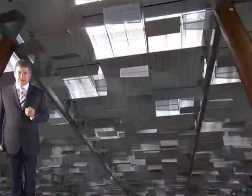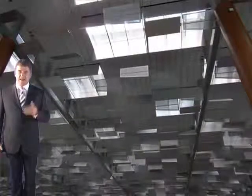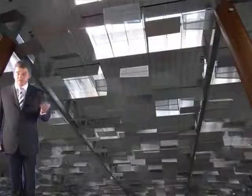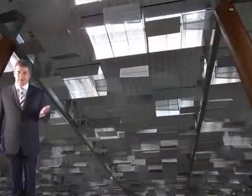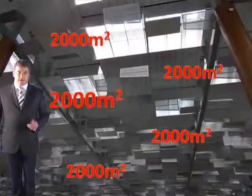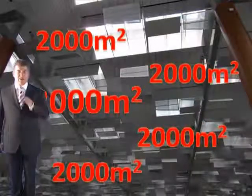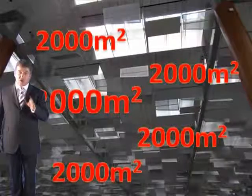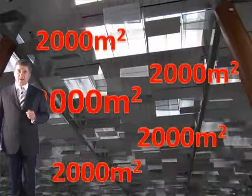Now the first thing to determine is the number of reservoirs that you're going to need in your building. So you need to work out how many reservoirs. For cost reasons, again, you're normally going to try and have the minimum requirement to meet the appropriate code. Now there are limits to the maximum size you can have for a reservoir. The maximum size for natural is 2,000 square metres. This can be increased to 3,000 square metres if it's for property protection only. Well, in this case clearly it's not. It is a life safety one, so you've got to maintain it at 2,000 square metres.